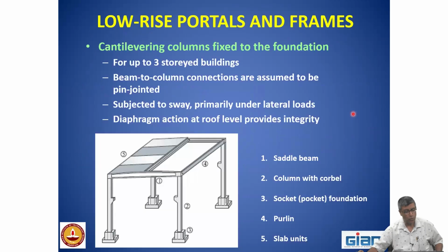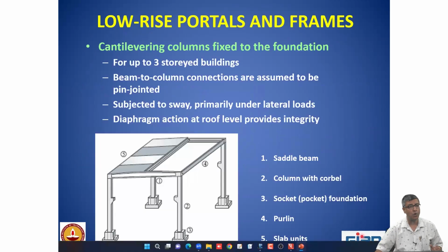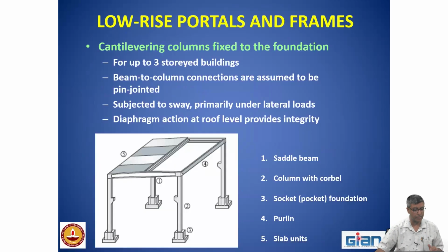If I look into the portals, let us try to understand how I generate the lateral load resistance. In a portal, yesterday Professor Leon Liberato pointed out that we need to fix the columns. They are like vertical cantilevers, okay. And in order to fix them, we use a type of foundation which is called a pocket or socket foundation.